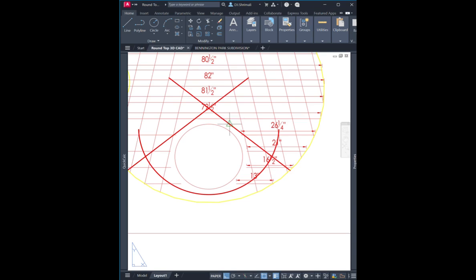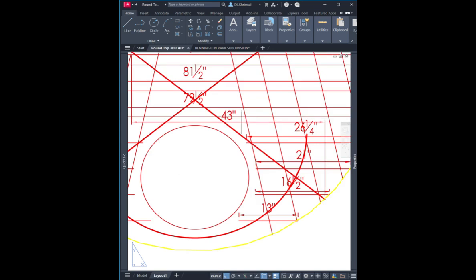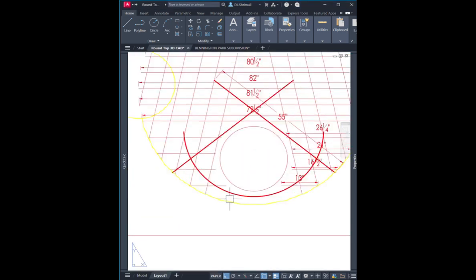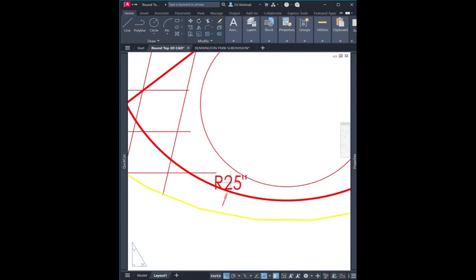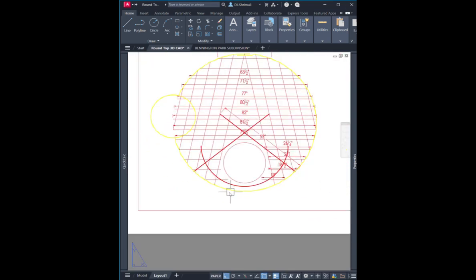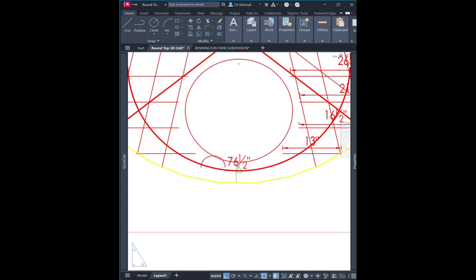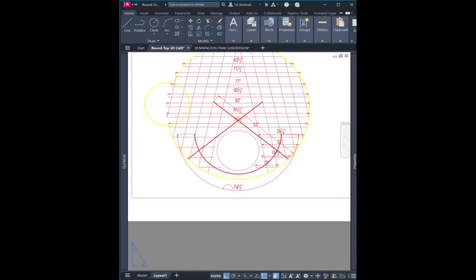And our diagonal rebars are like 55 inches, so I like to do it like 1.5 times the length of the opening, or 2.5. Okay, 2.5. So if you have a 24-inch opening, we'll just put a 5 feet diagonal rebar, approximately. Here I have used 55 inches, so anywhere between 2 to 2.5 is okay.